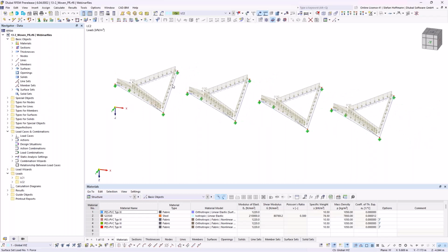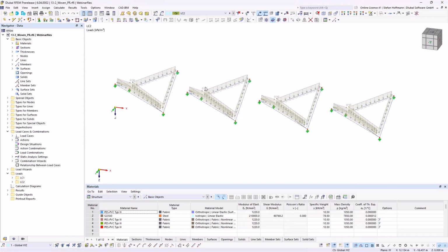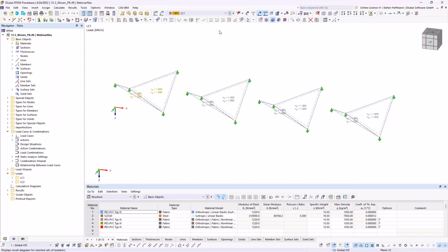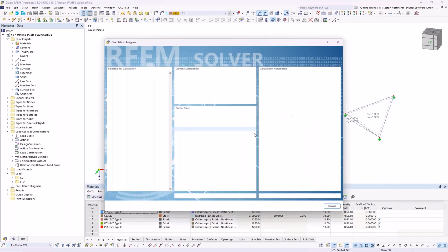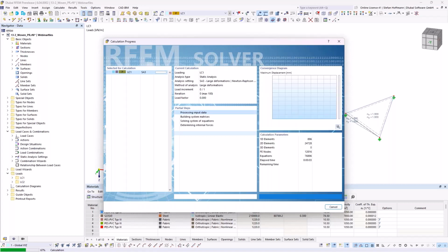And then there is a prestress we are giving, just a normal symmetric prestress in local X and Y direction with the standard method, so nothing special. And we then want to load it with a vertical load. Because during the prestress, so the form finding for the structure, we most likely define the shape we want to reach with our inner forces.